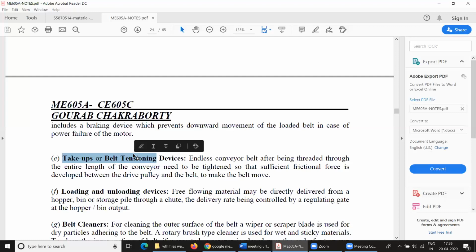Sideboards or skirt plates of considerable length, that is 2 to 3 meters, are generally attached to a conveyor structure to be placed centrally to the belt. It may be covering up to 2/3 or 3/4 width of the belt to maintain a small clearance with the moving belt. For unloading of materials at the end of the head pulley, no device is required excepting the proper chutes or guides to guide the discharge material.